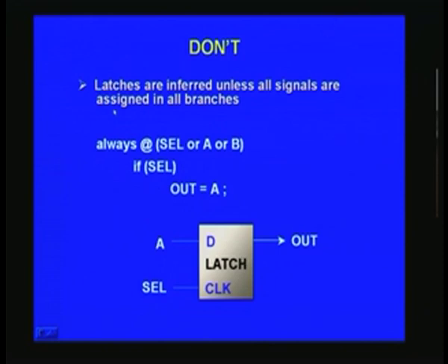And another thing that you should not do is omit that else. In the previous example we had an else here. If you omit that else, what happens? The tool will infer it as a latch. Latch is very detrimental because what is a latch?